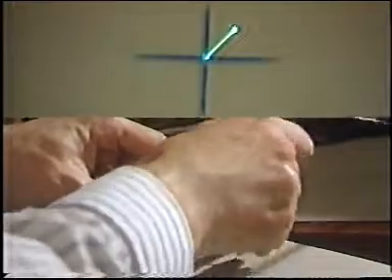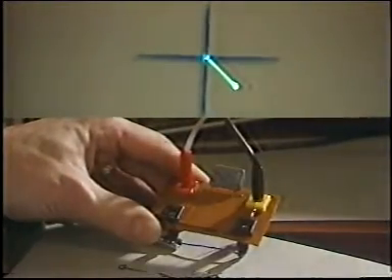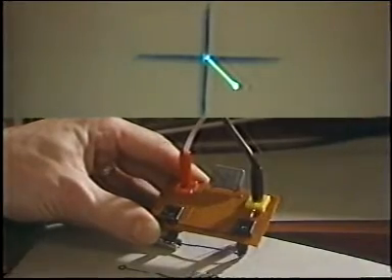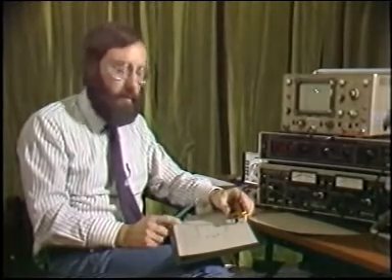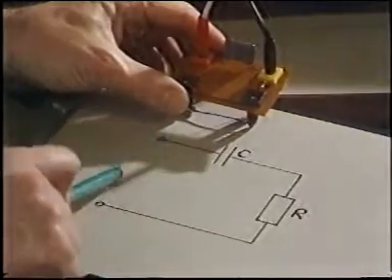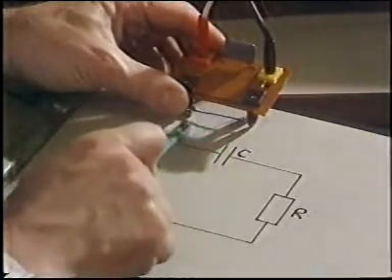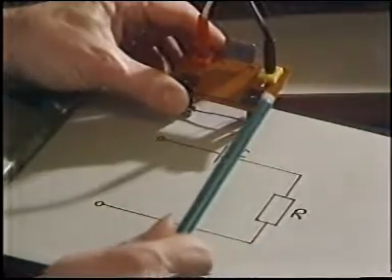And the voltage across the capacitor at a phase lag, again, of the order of 45 degrees. Now, Kirchhoff's laws apply to AC circuits as well as DC circuits, except that with AC circuits, we have to concern ourselves with phasors, so that the input voltage phasor is given by the phasor sum of the component phasor voltages.